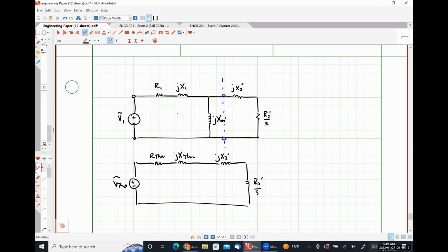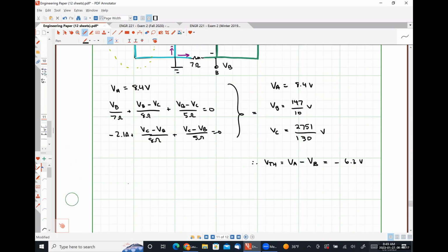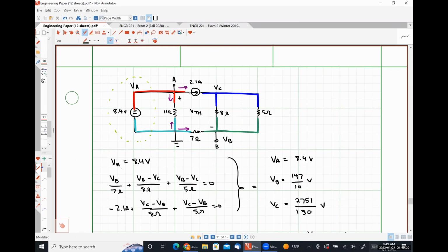So, the circuit we just did, test. And then we would measure the current through the short, but I would argue that that's going to be a 4 mesh thing. So just clear here. Our Norton current will by definition be this current. And the knee-jerk reaction to something like this would probably be to do mesh analysis, which would have 4 mesh currents. Some of you guys' calculators can take care of that. Some of you guys cannot.